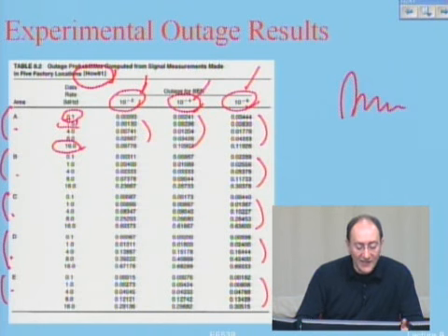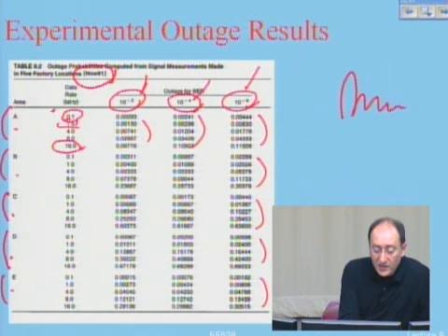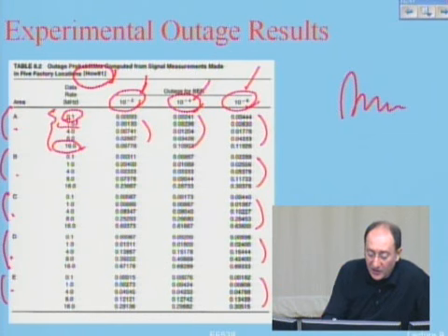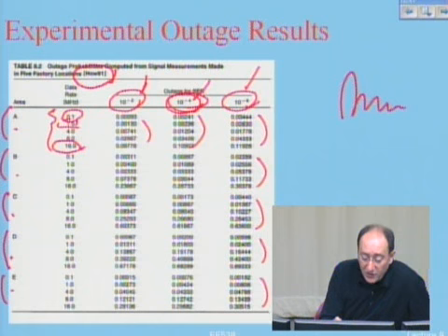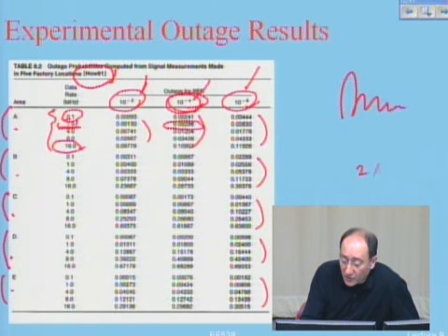Now, let's look at the first one, for example. In the first one, I see that in indoor areas I have error rates of 0.1, 1, 2, 3, etc. If I take the middle one, 10 to the minus 4, for my threshold, I see that at 1 megabit per second I have a probability of outage of 2 times 10 to the minus 3.